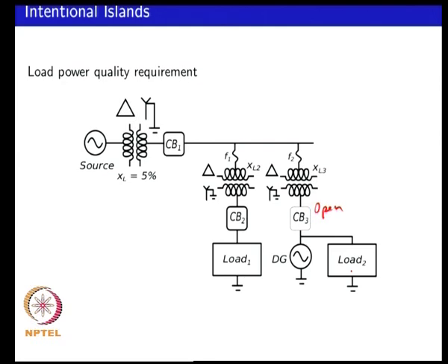You can also have a situation where, to address power quality, it may not be just your own facility breaker that you open. You might for some reason be capable of opening a breaker at the network and providing improved power quality on the feeder itself. It depends on whether your distributed generator has the capability to provide that level of power, both real and reactive. Also whether it can operate stably with such a big, wider network. You could also have other technical conditions which may need to be satisfied.